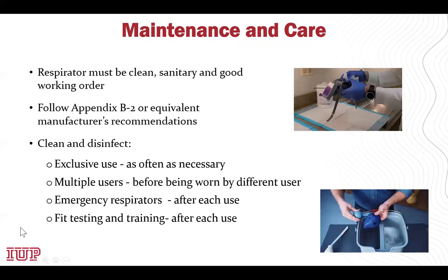Okay, now we're on to maintenance and care. Respirators must be in clean and orderly condition. We want to provide each user with a respirator that meets these requirements. Use procedures in Appendix B2 or equivalent manufacturer's recommendations. You want to clean and disinfect at the following intervals: as often as necessary, when issued for exclusive use, before being worn by different individuals when issued to more than one employee, after each use for emergency respirators and those used in fit testing and training.